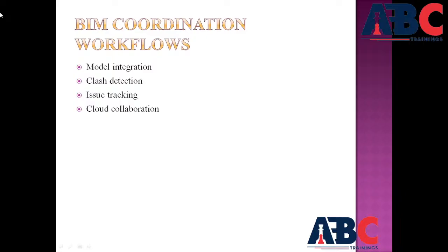So most of the things in BIM coordination workflows are combined, reviewed, and synchronized between the people. BIM coordination is about building digitally first to avoid mistakes physically later. Each discipline, architecture, structure, and MEP, develops its own BIM model, and these models are linked into a single comprehensive federated model with tools like Navisworks and BIM 360. The integrated model allows all users to view it together for holistic analysis.